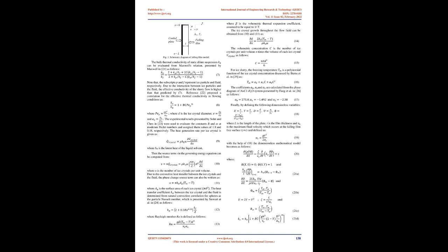Based on the assumptions mentioned above, the plate is maintained at a constant temperature that is lower than the freezing temperature of the solution. The heat is transferred as a latent heat from the suspended ice crystals to the surrounding supercooled fluid and then to the plate surface. As a result of this mechanism of pumping latent heat to the surrounding fluid, more ice formed, increasing ice crystal size. Using a source term to simulate the phase change, the governing steady-state energy equation can be expressed as follows.